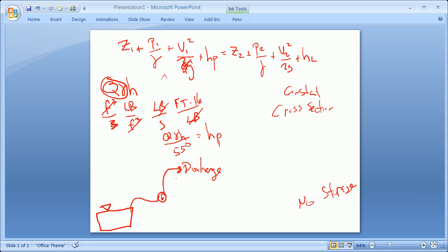And you have to realize that water flows down energy. And so if this discharge has a velocity head here equal to v squared over 2g, this is the energy. It has its elevation energy, no pressure. And if it's flowing down energy, the slope from that has to be positive up this way. This has to be flowing down. However, at the pump, if you now go back to the pump and go back to the water surface, this actually has to be flowing down energy, so it goes something like this.